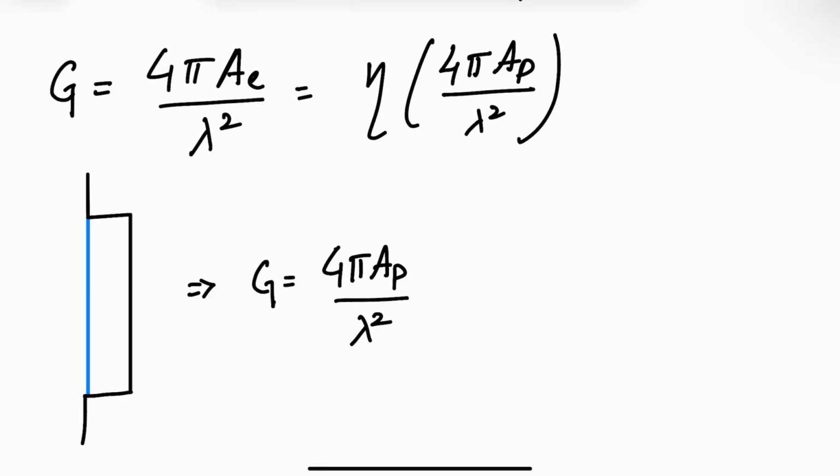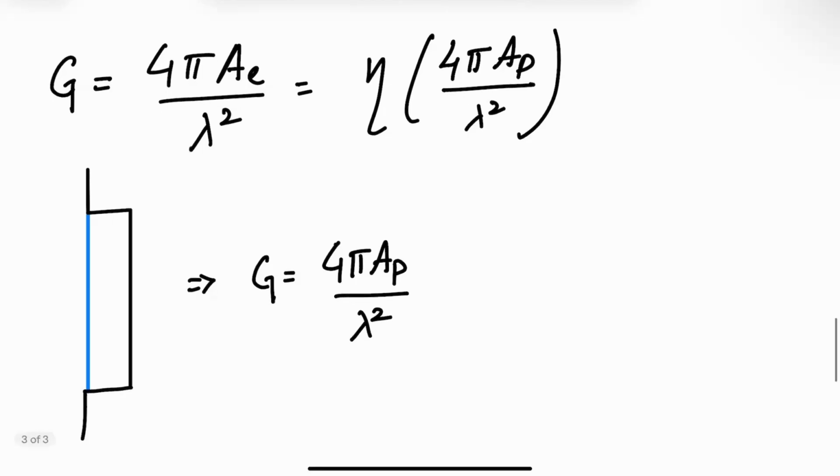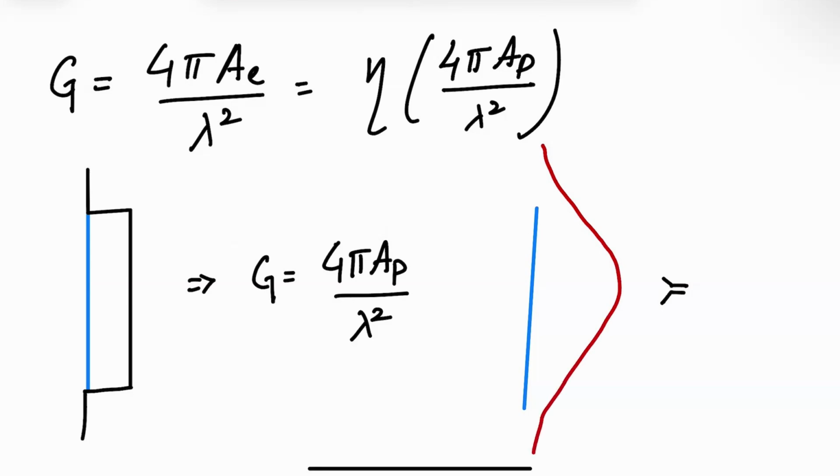But in reality, we know that when you illuminate a reflector, even if it's just a disk, so if I draw this disk again, the cross section of the disk, and I place a horn feed here, like that, then I know the illumination is not going to be uniform. The illumination will be something like this, right?